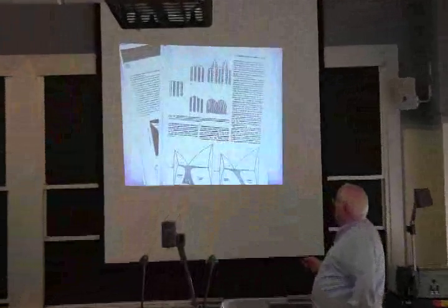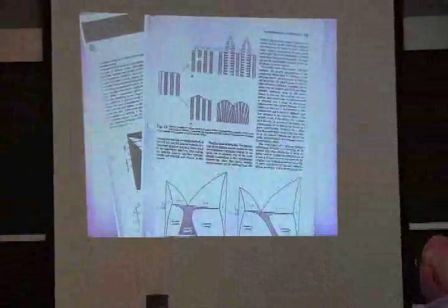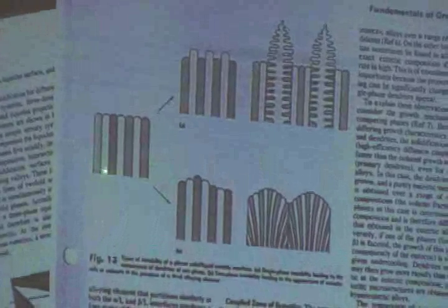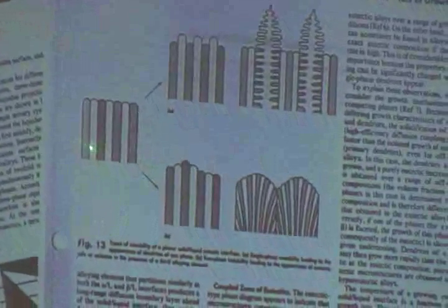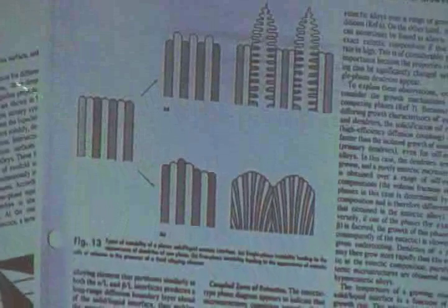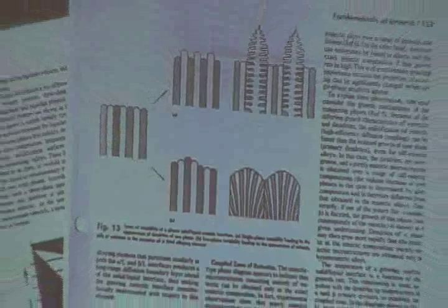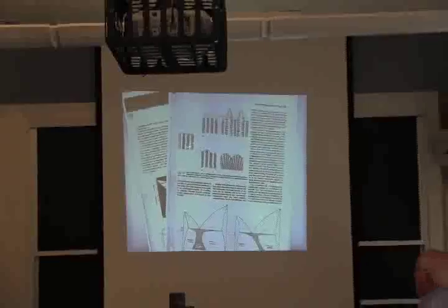If you look at it in a schematic, you actually will form 2 different phases in some alloys, and you can have cells grow where you have the alpha phase and the beta phase. Or, if you want to talk stainless steel, that could be cells of face-centered cubic and body-centered cubic crystal structure iron. One would be magnetic, one would be non-magnetic.